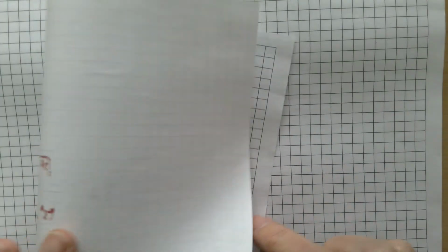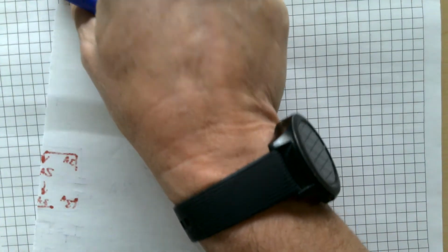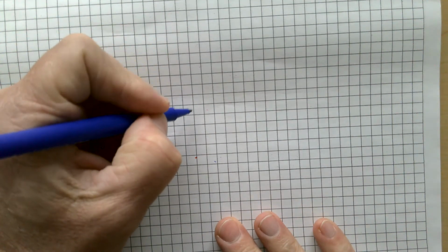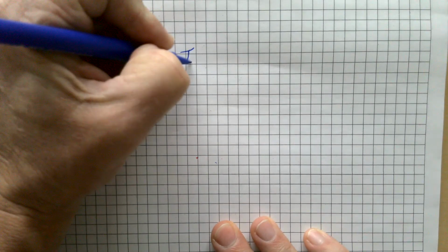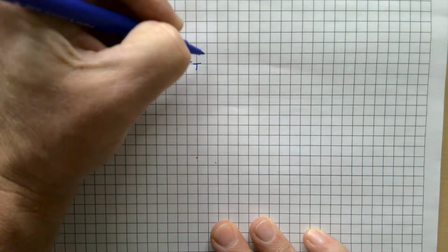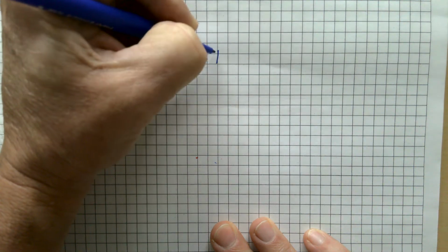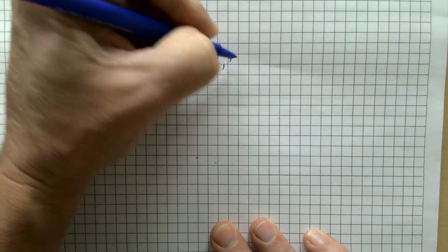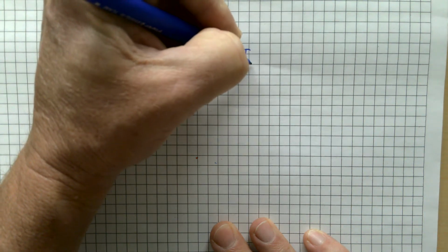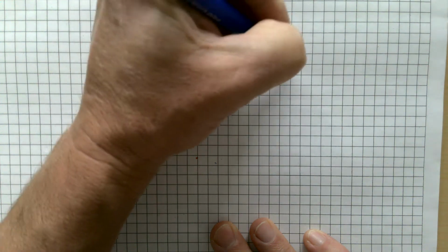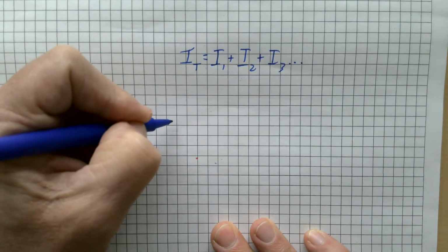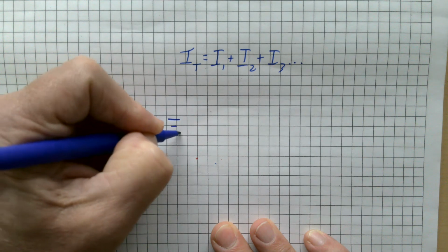We're not going to do the resistors yet because it needs to be a video by itself, because it has a whole different set of things to think about. But I want you to remember the next formula rule for a parallel circuit. We already know the first one we talked about: the total current equals the sum of the current used by each resistor or load, depending on how many we have. And we're going to draw another circuit here.